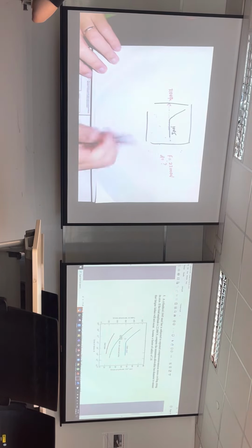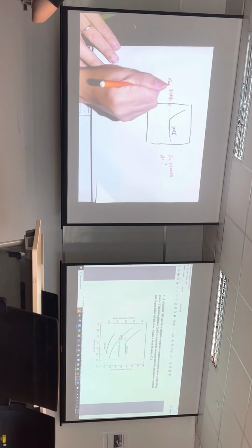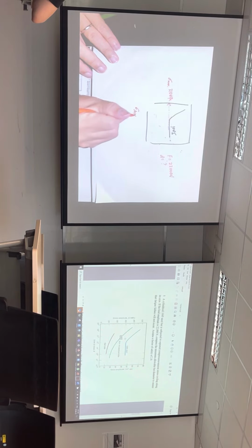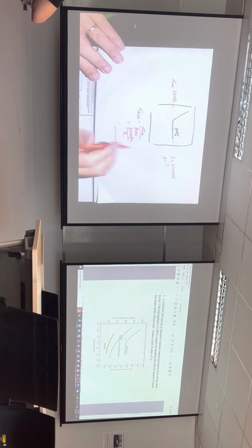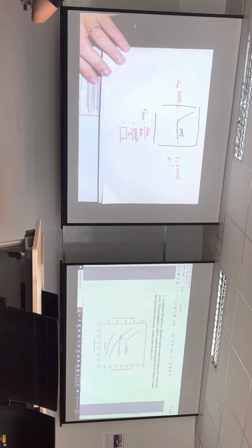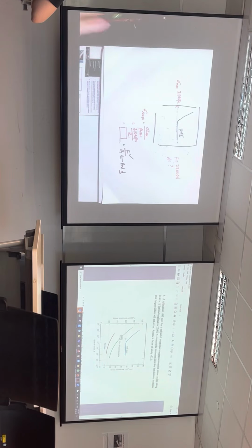So now, this is the max. Your design value will be equal to sigma max over the safety factor. So it'll be 310 megapascal over 2. So you have a certain value there. Based on this stress, it is equal to F over A.